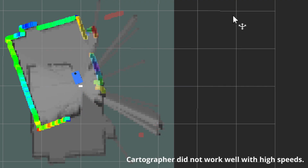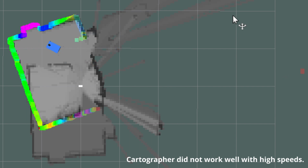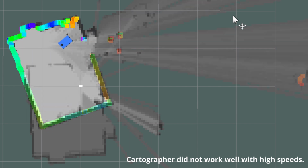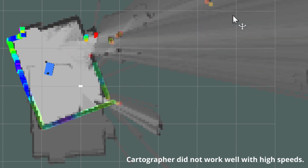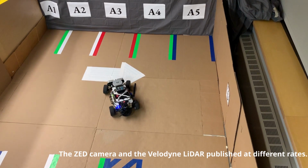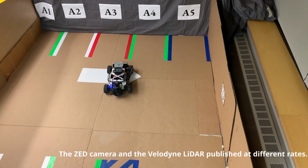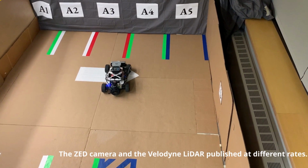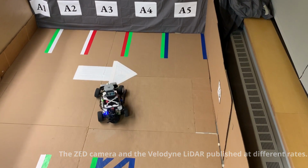Second, while running Cartographer, our 2D map would shift when we drove fast, which caused inconsistencies in coloring. The effects of this were mitigated by tuning the Cartographer parameters. Third, our Z camera was not as fast as our LiDAR, so we had to stop while mapping to make sure both data sources were seeing the same thing.